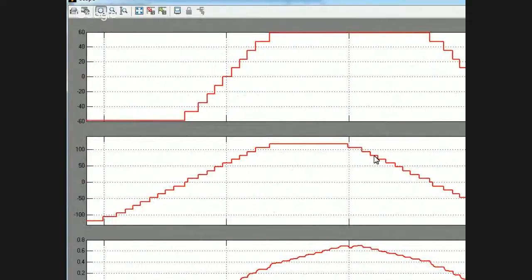The 11 level. So this is the phase voltage: 1, 2, 3, 4, 5, 6, 7, 8, 9, 10, 11. So this is an 11 level inverter. You can get 11 in phase, and in line there will be 21. So 22 minus 1, that will be your line voltage. Line voltage means you will have 21 steps.